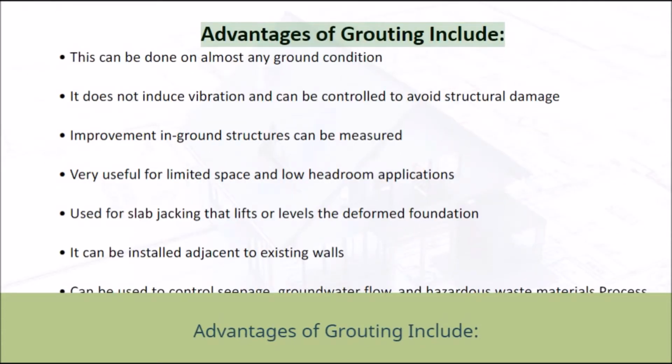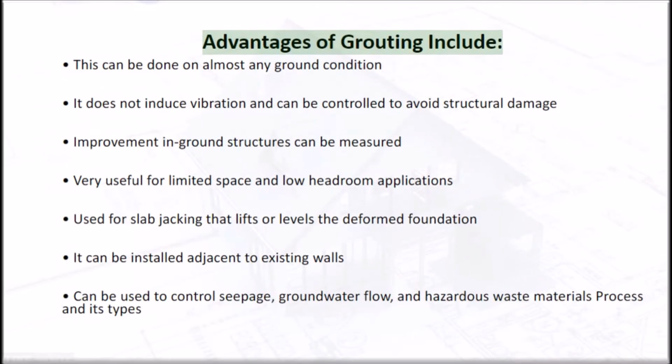Advantages of grouting include: this can be done on almost any ground condition. It does not induce vibration and can be controlled to avoid structural damage. Improvement in ground structures can be measured. Very useful for limited space and low headroom applications.